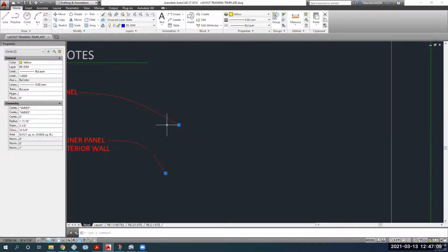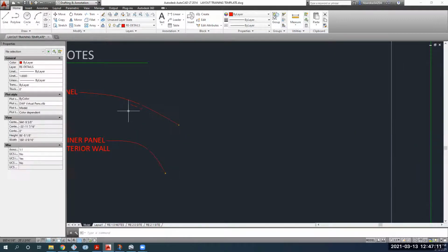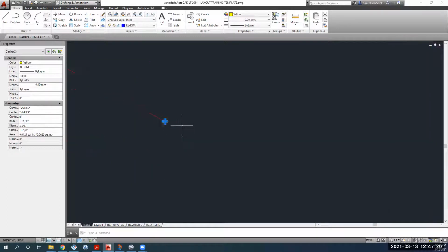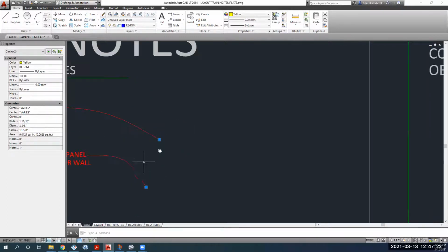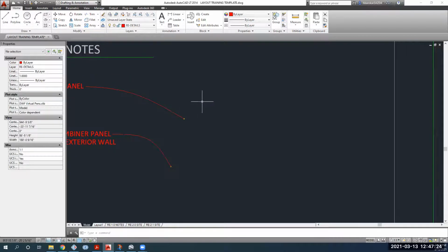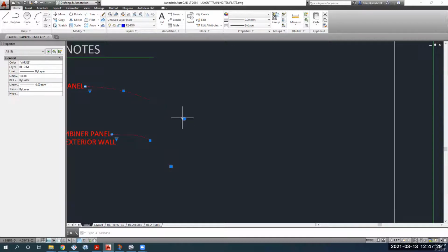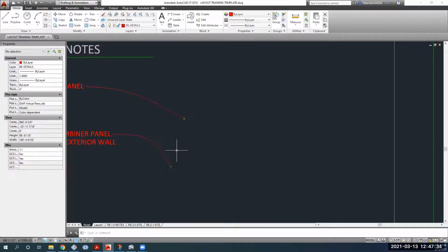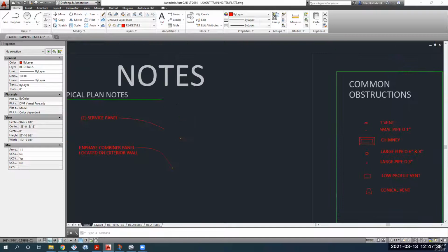You see that right now these two line segments were completely outside of this blue rectangle, so they did not get selected or highlighted with those little blue dots. But when you go from right to left, it selects everything that comes in contact with that green rectangle. Got it? Yeah, this is a pretty handy tool in AutoCAD, and once it becomes intuitive, it works really fast.